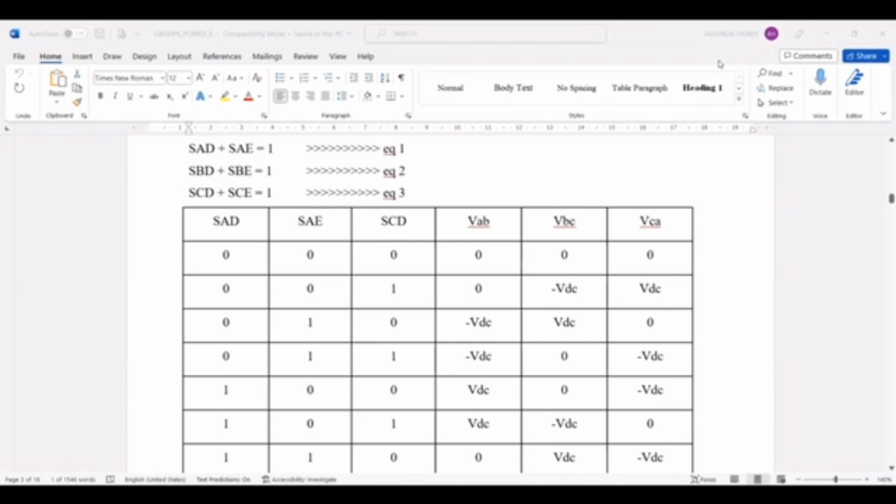In our simulation, the complete three-phase voltage source inverter equivalents are displayed. We use a 3-phase voltage source with controllable voltage amplitude, phase, and frequency, using the SPWM technique, three sine waves and a high frequency triangular carrier wave.